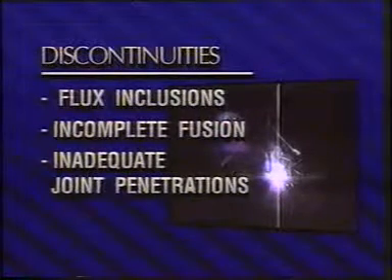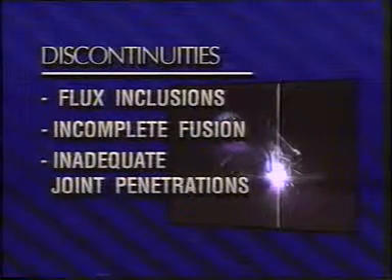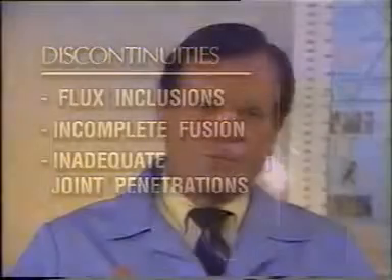Under low cycle fatigue, the fatigue life of many metals is independent of grain size. In contrast, under high cycle fatigue, the fatigue life of many metals is increased when grain size is reduced. However, the effect of grain size on high cycle fatigue properties is difficult to assess, since many microstructures are altered by the same treatments that alter grain size.